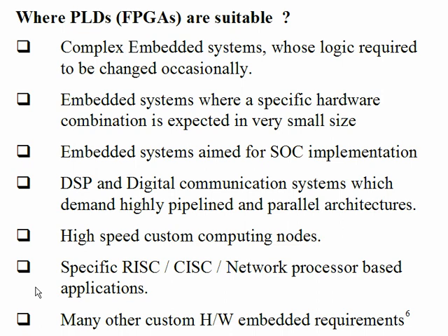But when you come to 8086, you see it clearly, correct? In the 8086 block diagram, you have seen there is a pipeline unit, with some pipeline stages. So in all the modern processors, you have pipelines. You have pipelining in RISC, you have pipelining in CISC also. But in the case of RISC, pipelining will give the benefit the majority of the time, in any kind of instruction sequence. But in the case of CISC, because I have one instruction which takes 4 clock cycles and another which takes 30 clock cycles, even though I design some pipeline unit, the usage of the pipeline becomes less when you compare with RISC.